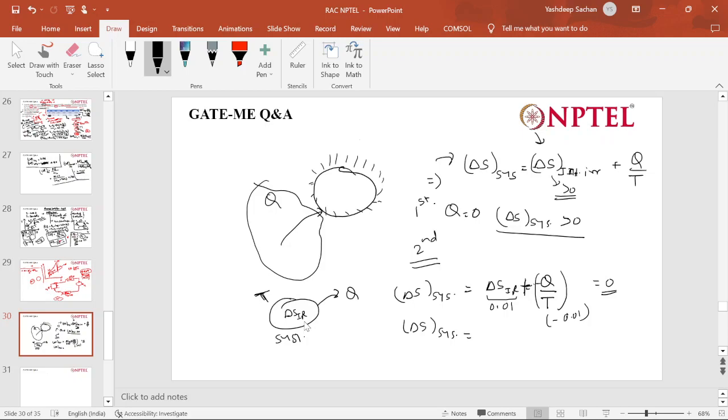Okay, so what will be the net entropy of the system if the case is reversible plus adiabatic? If it is reversible, then the delta S of internal irreversibility would be 0, correct? And due to the adiabatic condition, Q is 0. So it is also isentropic, right?